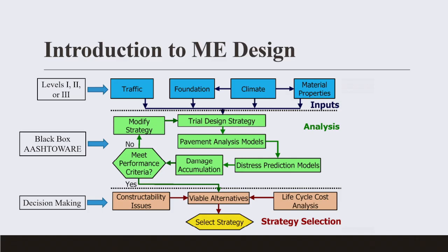So basically, the pavement analysis is modified, it's able to predict distresses, damage factor accumulation, whether it meets your performance, and then you keep on modifying your strategy. So, okay, based on this, I want to increase the thickness of the pavement or reduce it, maybe use a more dense material. So you are actually involved in the design process within this black box.